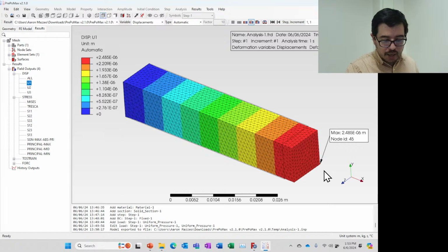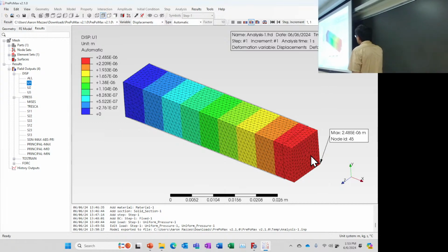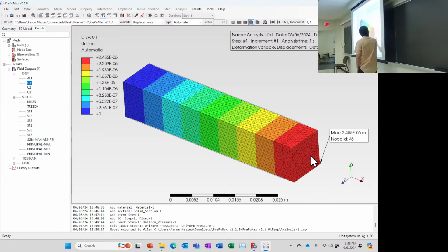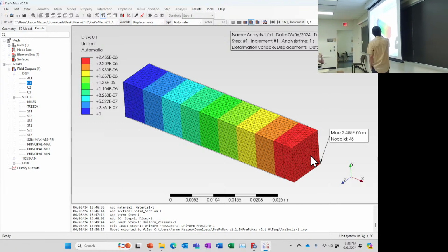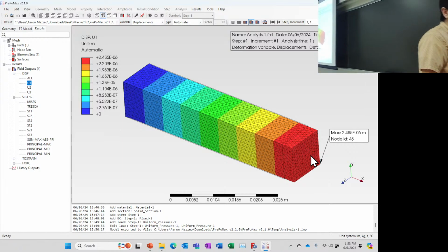It's telling us that the max displacement is here at this bottom corner. In reality, maybe it's around here, whatever. But you see that? Because this is displacement, it's also illustrative. Yes, I applied a stress here, but imagine that this were a spring. We've talked about this. This part over here is going to be displacing less than this part over here because there's a lot more length to it. Delta is equal to PL over AE.